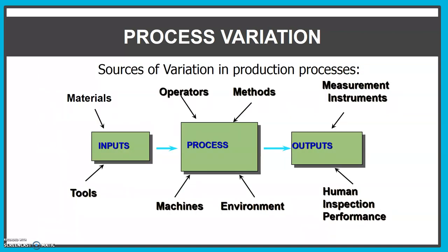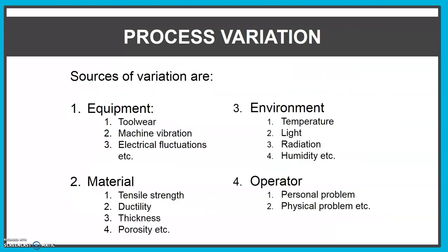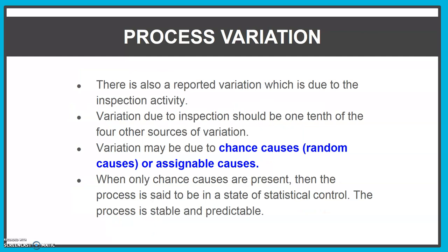So in the previous slide, I stated that the variation comes from 4M1E. So 4M1E: equipment, maybe using different equipment, tool-wear problem, machine vibration problem. All of these are where the variations come from. Okay, all the variation we can summarize into 2 types of causes. First one, we can say the variation is a chance cause. It's a natural cause.